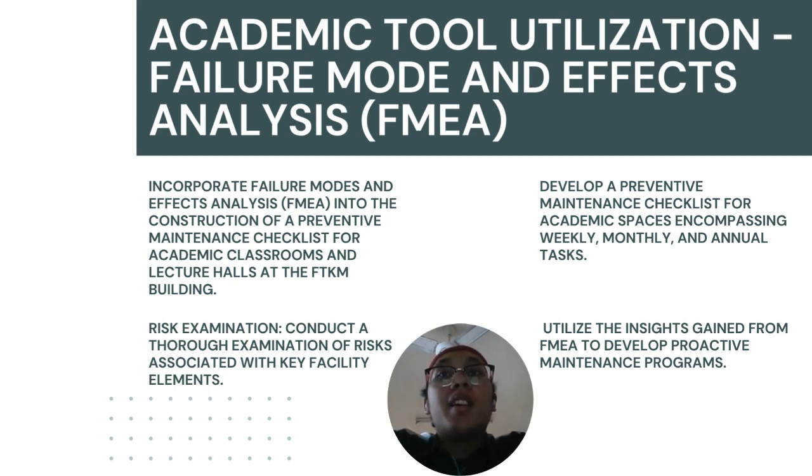For the second one is risk examination. Conduct a thorough examination of risks associated with key facility elements. For the third one is to develop a preventive maintenance checklist, whether weekly, monthly, or annual tasks. And lastly, utilize the insight gained from FMEA to develop a proactive maintenance program.